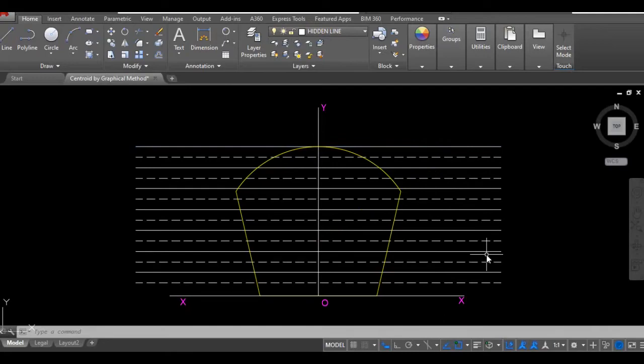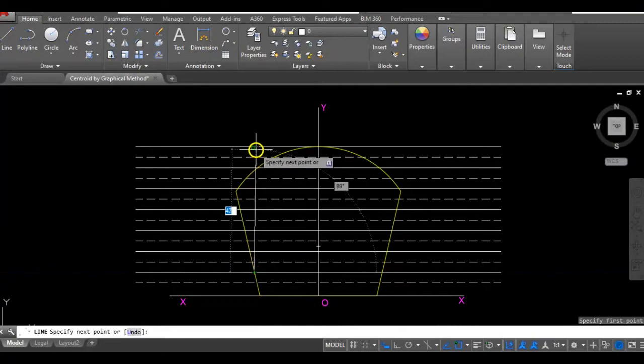Now you have to be mindful of the horizontal lines that you have. And remember, ordinates are solid, mid ordinates are hidden detail lines. So that would make our process a little bit easier. To get our first derived area, we're going to be starting with our ordinates. So what we do with our ordinates, and I'm going to put this back to 0, select where the ordinate intersects with the shape and bring that up.